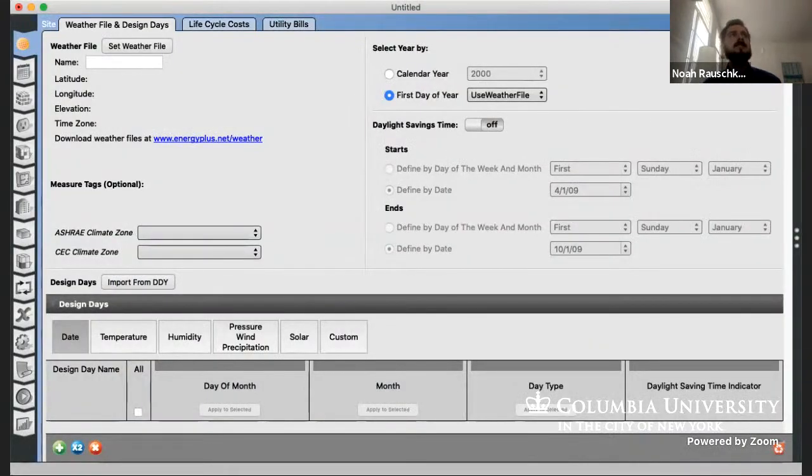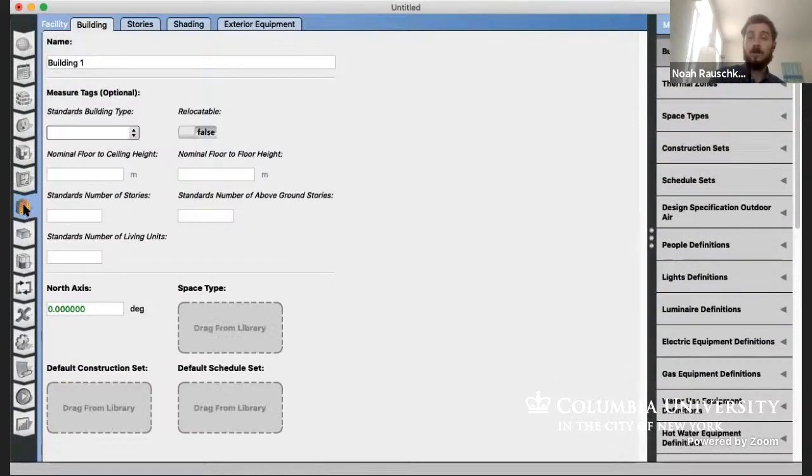So something that exists is called OpenStudio. I've got the Mac version open right now. And this is an interface, kind of like the IDF editor, for going in and specifying construction of a building and specifying all the zones. And back in my day, it worked with SketchUp, which was really incredible. So you open SketchUp, and anybody who's used SketchUp knows that it's a really fun tool for building geometries.